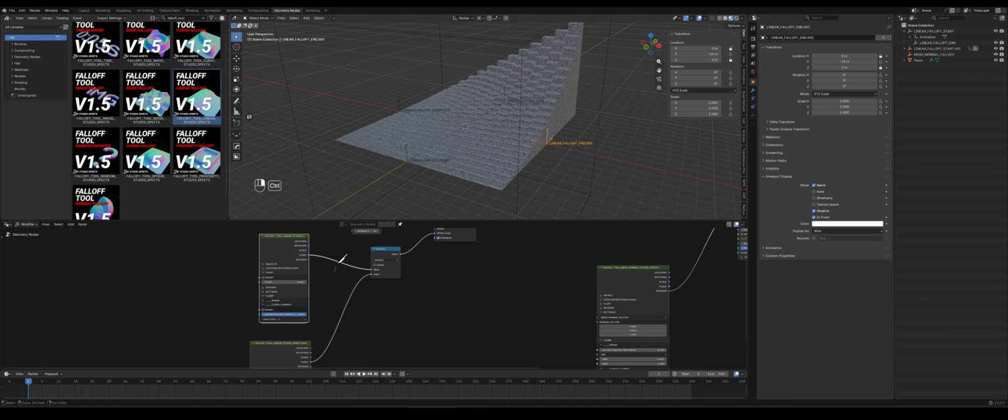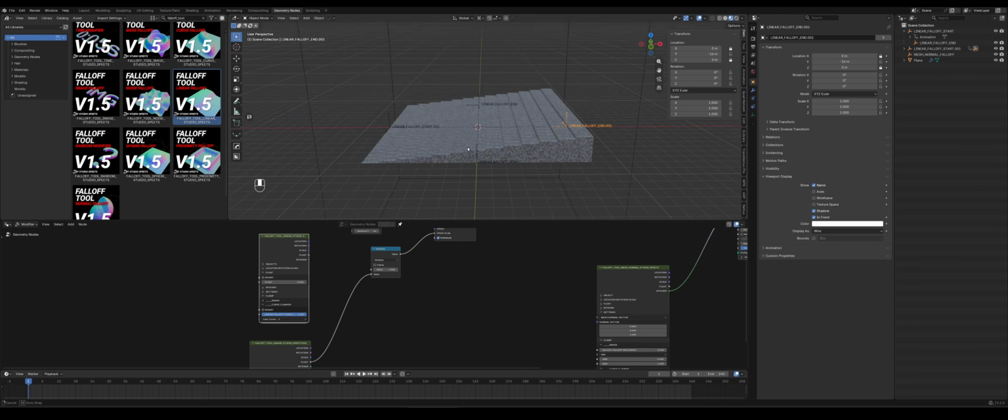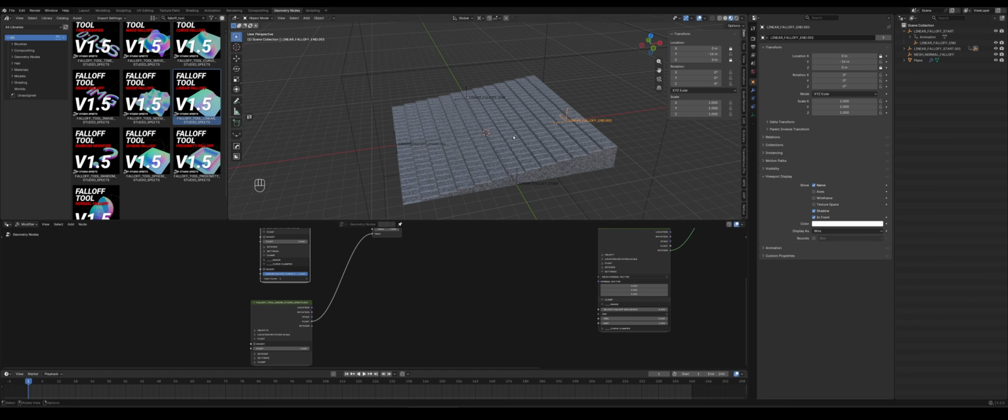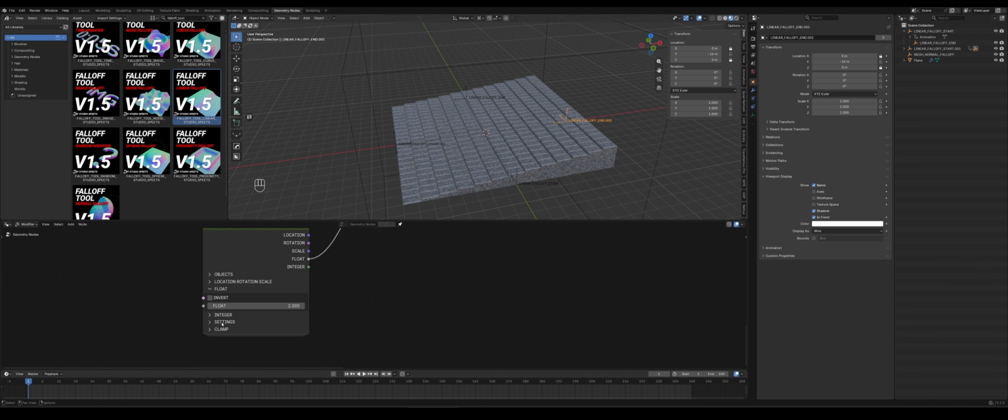But let's just undo that one. So now the second linear Falloff is only connected. Under settings under the linear falloff, we can also select mirror linear falloff. So right now it goes from A to B, or start to end, and the mirror linear falloff goes from A to B to A, and the B is in the middle in this case.